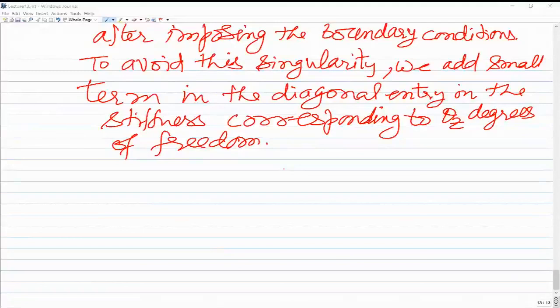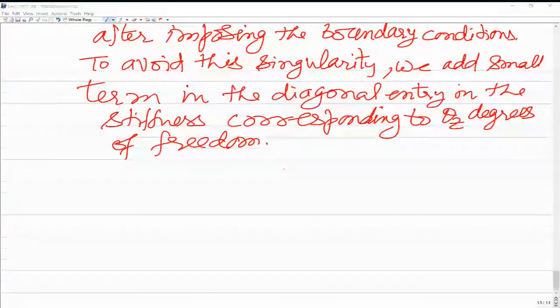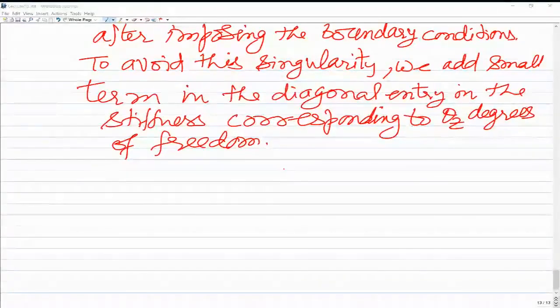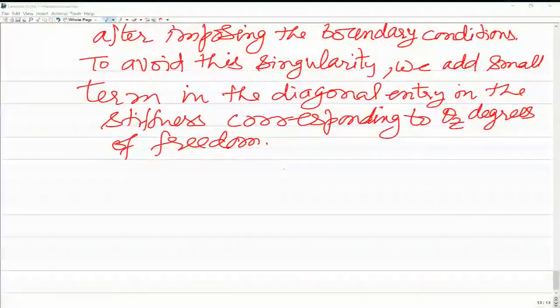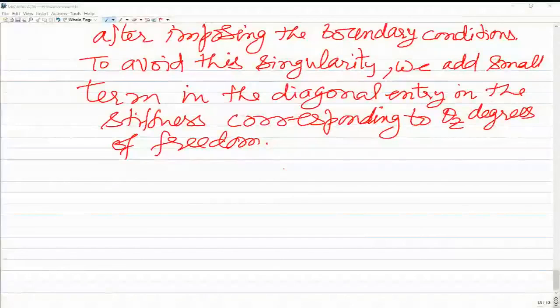So anybody else? Any other question? Sir, one more question I had. In the last step you pre-multiplied the equation by T transpose to express the forces with respect to the global coordinate system. Yes, sir. But initially, when we had written these forces like F external, it was according to our small xyz. Right. So when you look at the load vector, that will be basically with respect to the small axes. If you look at them, they will be along the small x, y, and z axes.